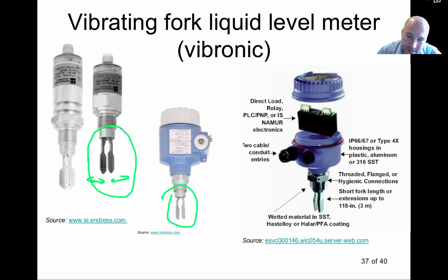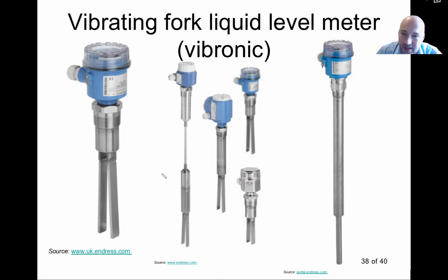So you can see also how this is mounted in the tank wall. It's mounted from the side here with this thread, and this sticks into the liquid, and this is outside of your tank. Here the same, this is the thread, and this is outside of your tank. It can also be hanging from the top of your tank, so then it looks like this. You can see either a cable or a stainless steel rod, and at the ends you have those two forks, and they're vibrating, so this moves back and forth, and you detect again if the vibration stops or if it changes the amplitude. So it's very simple in mechanical terms.